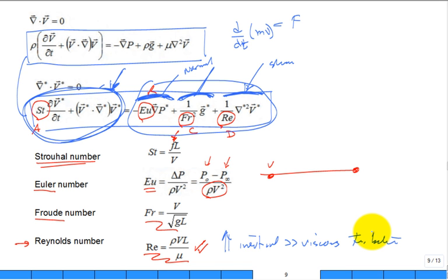So if I was to take this equation, this is our full Navier-Stokes. Before the full Navier-Stokes was developed, there was a simpler set of equations, and they neglected this term right in here. When they neglected that term, what did they neglect? The shear stresses, the viscosity. It was frictionless flow.